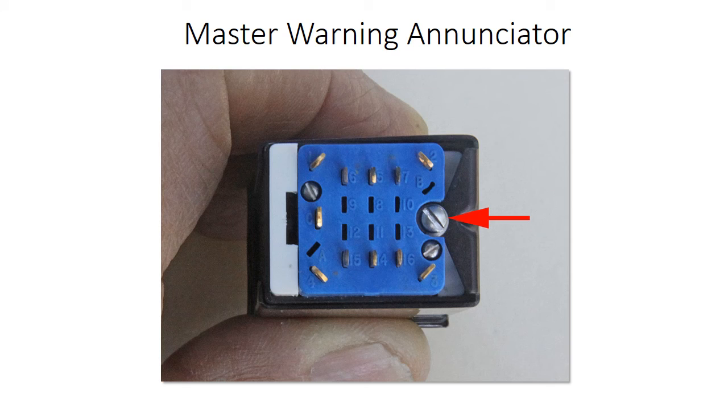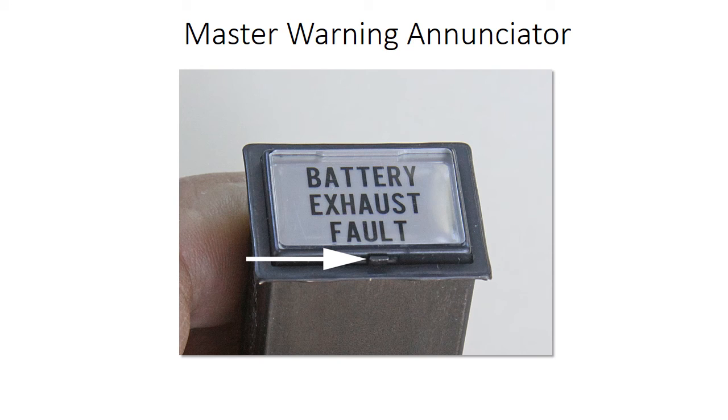This is the rear of the back side showing the individual contacts for the lights and the push button switch. And I've got a red arrow that's pointing to that screw. So that's the screw that pulls the whole assembly together and locks it on the panel. These units relamp from the front. So if you burn out a light on the front, and there's 4 of them in there for redundancy, you don't have to tear into your instrument panel. You push on that little bitty tab that you can see pointed to by the white arrow. Push that over about 1/8 of an inch, and that assembly comes out from the front.